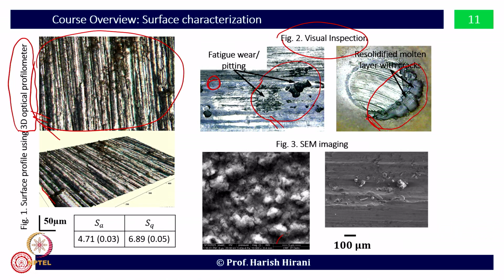Now, we want to go ahead with much more detail even on the surface, so I go to a 5 micron level, a much lower level, and I can see here some sort of salt formation, or some chlorine action happening on the surface itself. In this situation we know this is initiation, and naturally the possibility is that the delaminated surface will start disintegrating and create wear, and many times wear itself leads to a major failure. Even though we say that wear is a very slow phenomenon, if we are able to stop it there itself, it will not lead to a major failure.